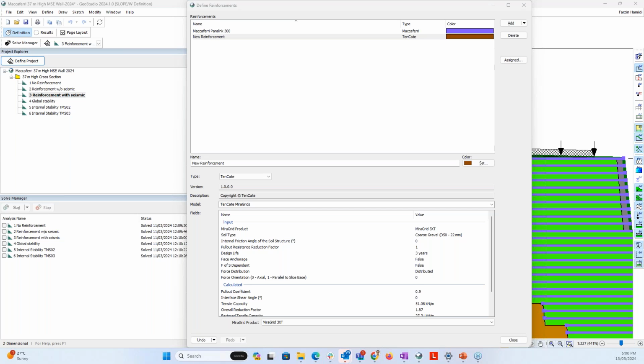So the rainfall, yeah, that's a good question. Check the stability due to rainfall. Yes, we do have the option to include it, but you need to couple SEEP and SLOPE together. So you need to couple SEEP/W analysis and SLOPE/W analysis if you want to consider the rainfall effect. You can consider the boundary condition as an infiltration and incorporate the rainfall effect into your SLOPE/W by updating the piezometric surfaces.